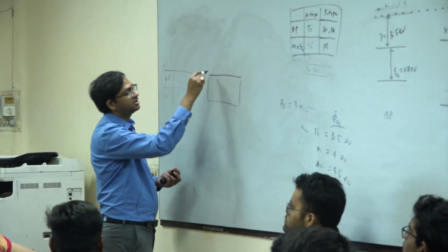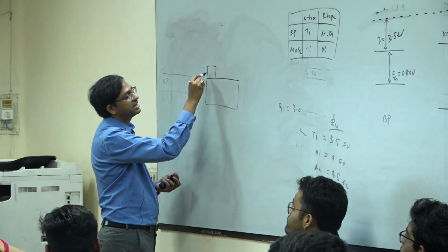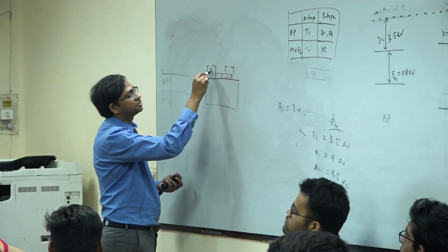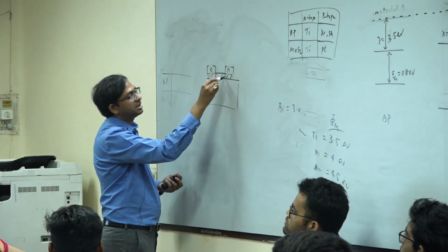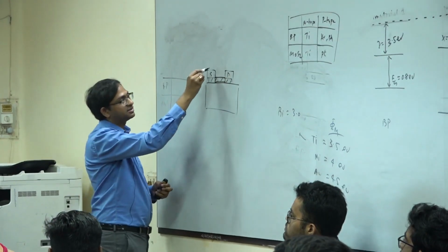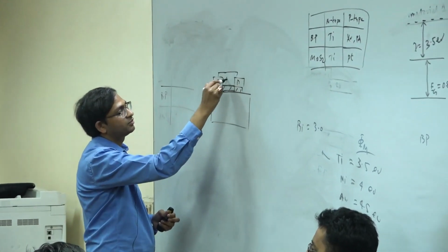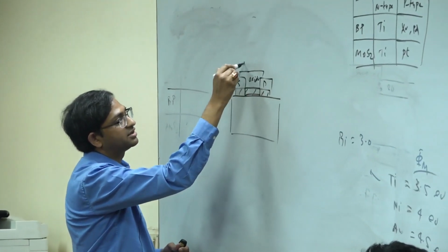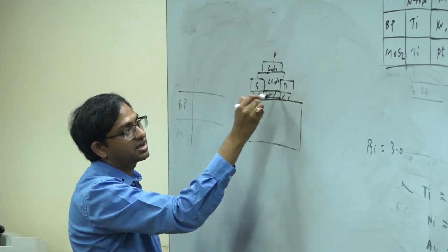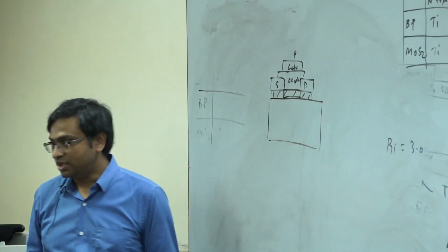So this is our semiconductor structure. Source, drain, and then I have this channel, source, drain, right? And this channel is something we want to be a semiconductor, right? And there is a gate. So there is some oxide, and then there is a gate. And what I want to do is change the conductivity of this by applying a gate voltage.